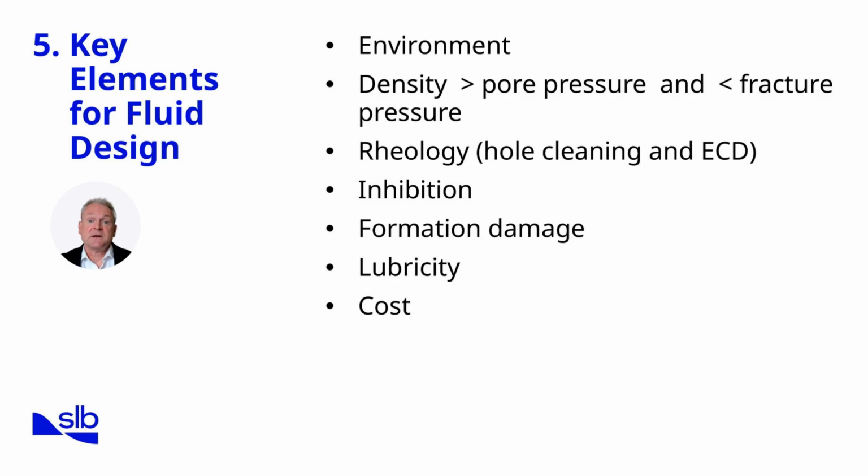Next, we consider rheology, which controls hole cleaning, cuttings transport, and equivalent circulating density, ECD. Proper rheological properties prevent cuttings beds in deviated sections and maintain wellbore stability. Inhibition is equally important when drilling through reactive shales, preventing swelling or disintegration.